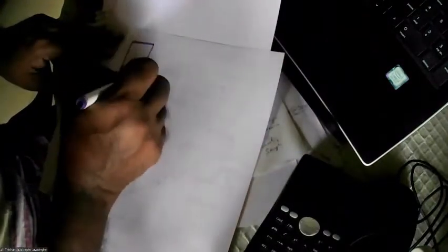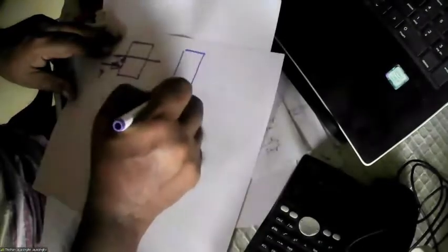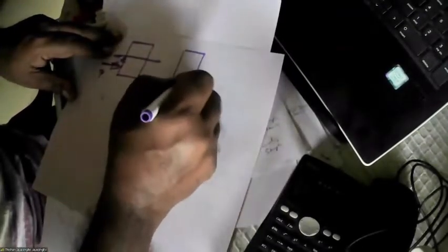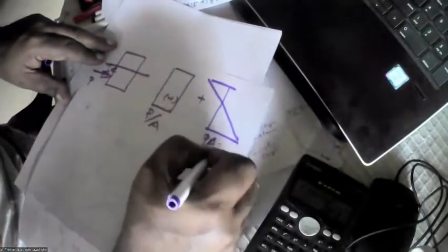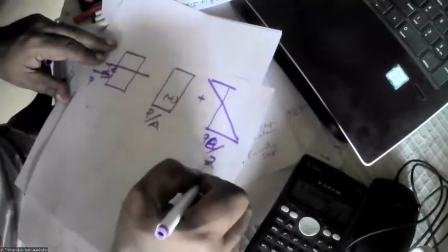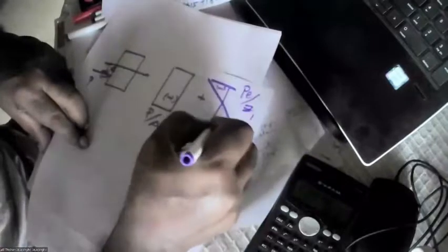Then we can write an equation. Under transfer conditions, we apply a P at an eccentricity. So we get P over A positive, plus compression at bottom, tension at top: P e over Z2, and P e over Z1, which is a negative quantity, because Z1 is negative.